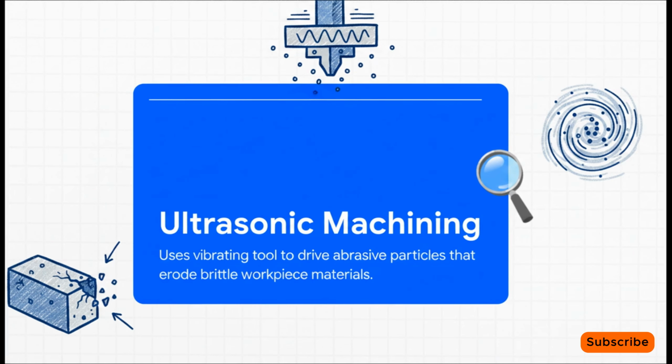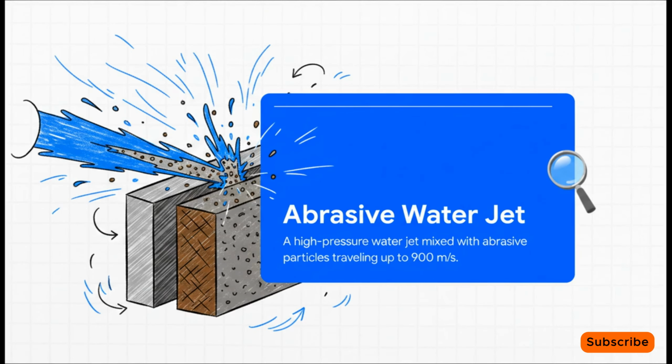Now, the crazy part is, the tool isn't actually cutting the material directly. Instead, that kinetic energy drives tiny, abrasive particles, which are suspended in a slurry, right into a brittle workpiece. These millions of microscopic impacts essentially fracture the material away, making it incredibly useful for fragile stuff like glass, ceramics, and quartz. Taking kinetic energy to the absolute extreme, we rely on high-velocity jets.